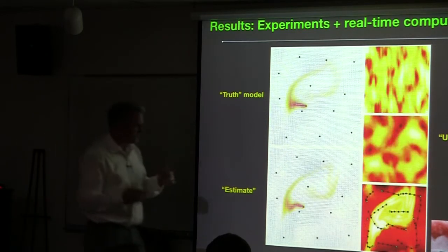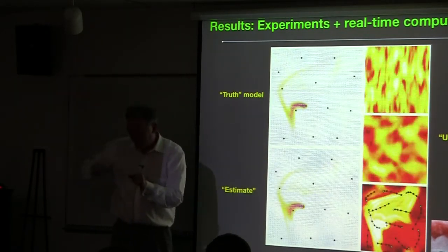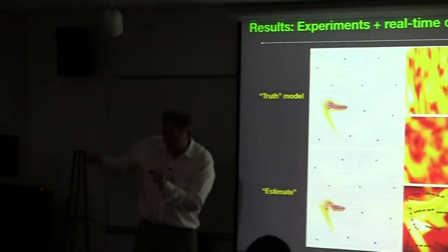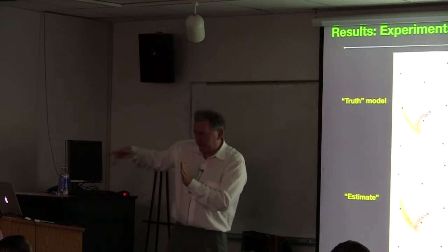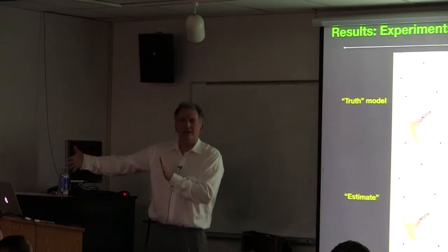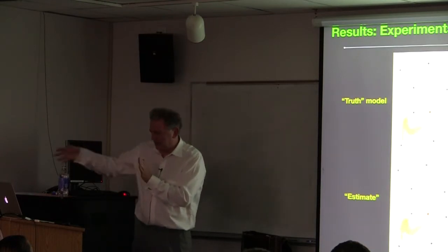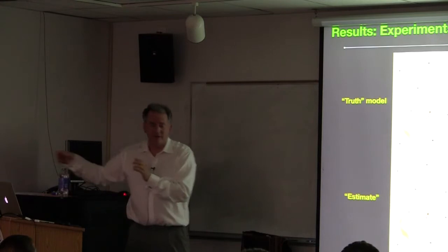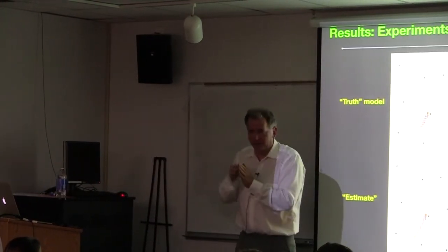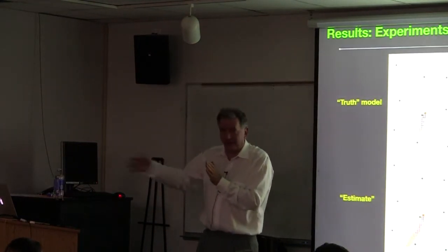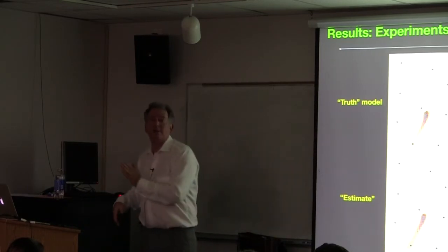In the model predictive control setting, for each of the vehicles as they're moving along, we're looking into the near future and going back and forth, asking what trajectory over the near future those vehicles should be moving on in order to minimize the trace of the covariance at the forecast time. And that is running constantly as the system evolves. I was shifting my body as this was going, because time is evolving as I'm doing this calculation. This calculation goes really fast, looks at a bunch of prospective trajectories of where these vehicles will go, and time is evolving as it goes along.